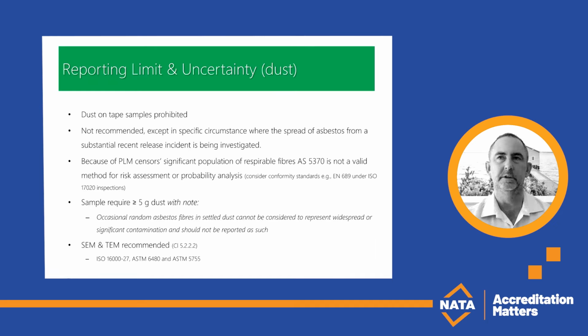And looking at dust, there's been some ongoing debate regarding the use of dust on tape samples. The new Australian standard explicitly prohibits this sampling method, and in general, dust testing is not recommended except in specific circumstances where asbestos release is suspected under investigation. Historically, settled dust testing has been mentioned in older documents from the National Occupational Health and Safety Commission, particularly in the context of clearance inspections. However, it's essential to note that settled dust testing is not a verification method for clearance inspections and should not be used for this purpose.